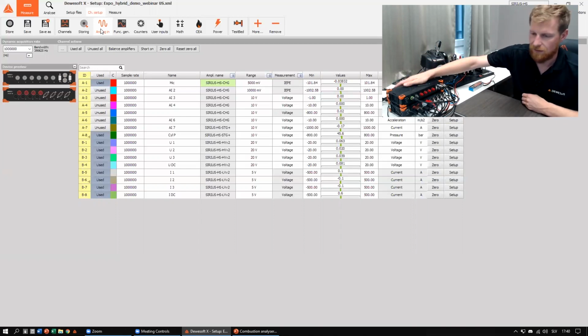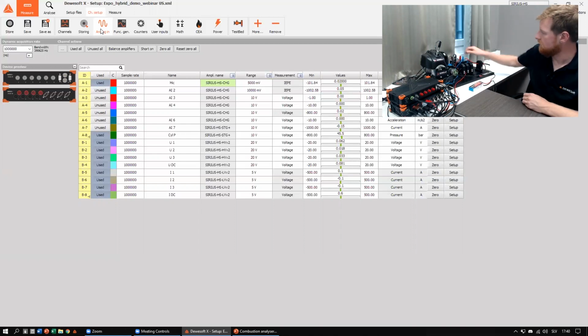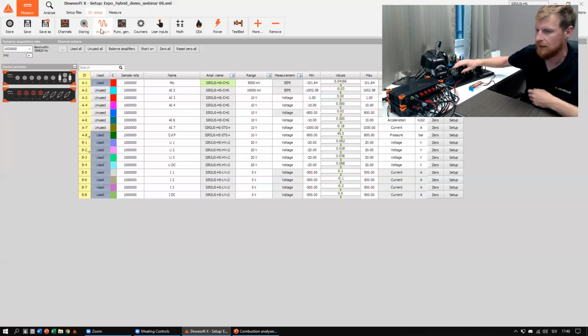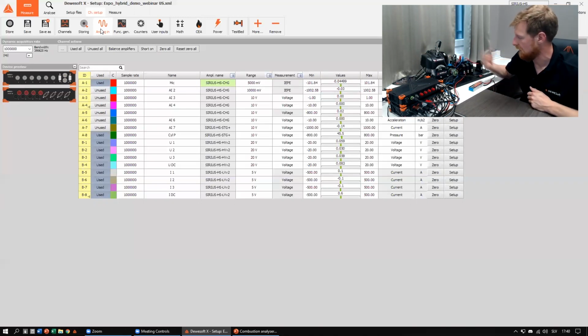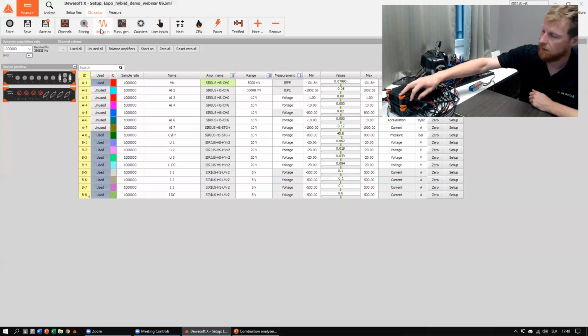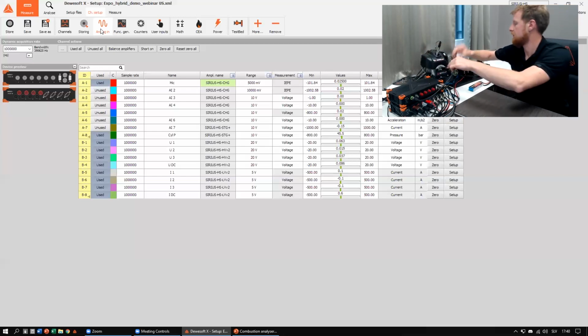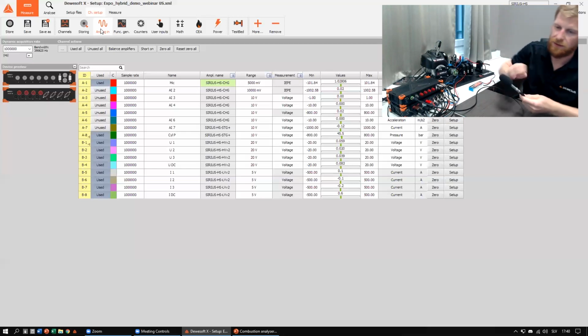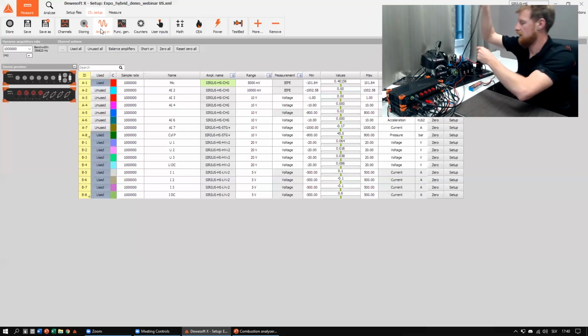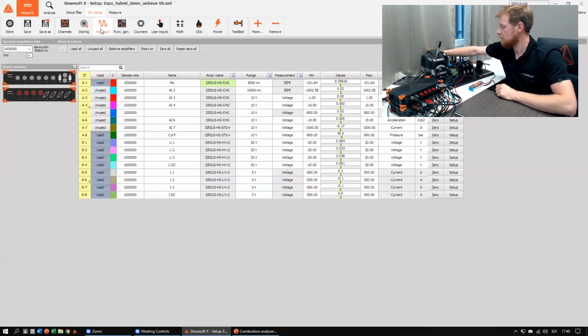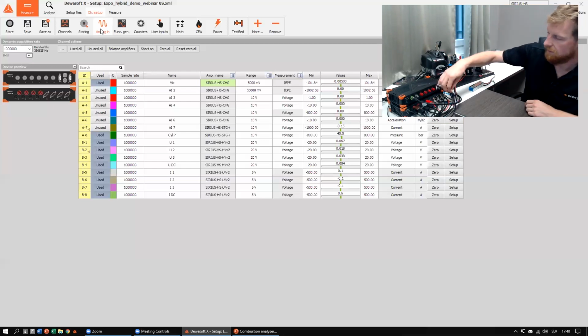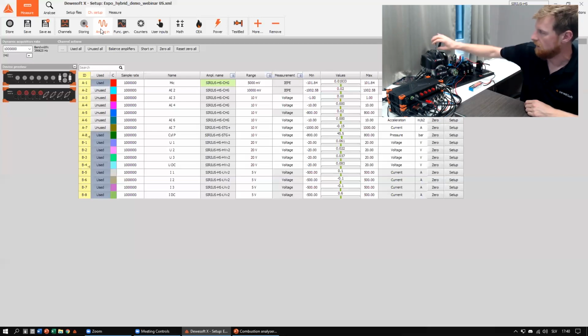On the backside of the SIRIUS unit, we also have an analog output through which we can control the controller for this electric motor. So we send out a pulse and tell the engine when to run and with how many RPM. On the front, we have in the first input just a simple microphone connected, so we can measure exhaust noise. And here in the front, on the counter input, we have the encoder connected. And here we have the pressure signal connected to the STG input.